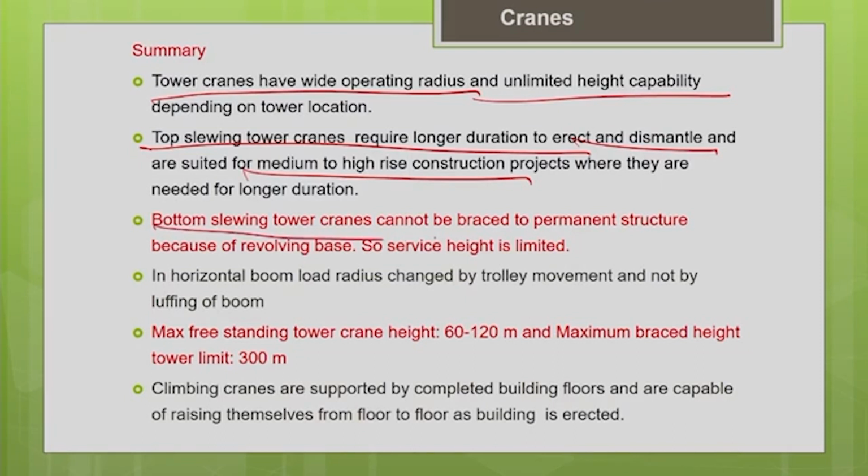For bottom slewing tower cranes, you have a height restriction. This is because here the tower will also rotate, you cannot brace it to the permanent structure, so you cannot go for a greater height. So, the service height of the bottom slewing tower crane is limited.